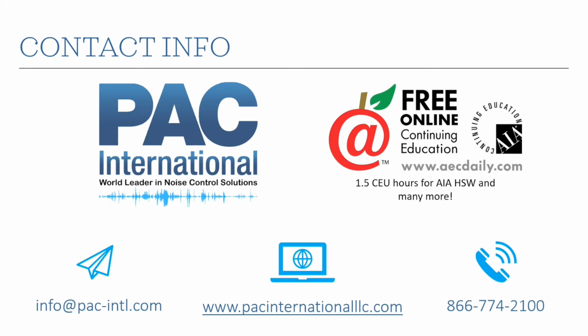So the big performance difference between the RIIC clip and resilient channel, even with the Boost, is that the RIIC clip is like quality assurance of performance in the field. And if you're interested in the issues with resilient channel, both from a design standpoint and a construction installation standpoint, ABD Engineering and Design, an acoustical consulting firm here in the Portland area and my former employer, has 2 really good blog posts about resilient channel. You can just Google ABD Engineering resilient channel and you should be able to find them.